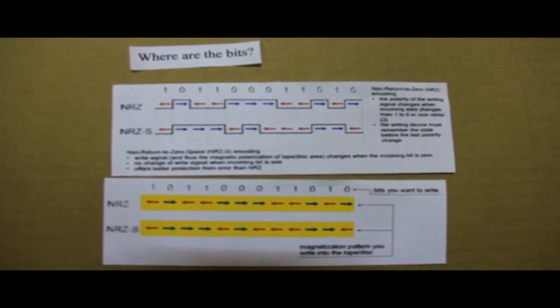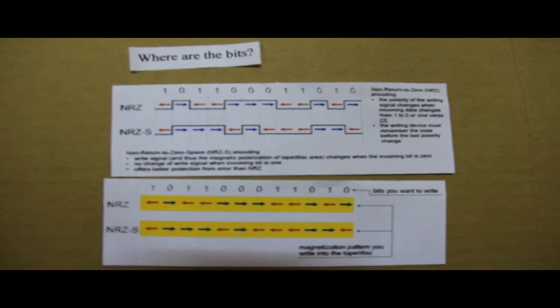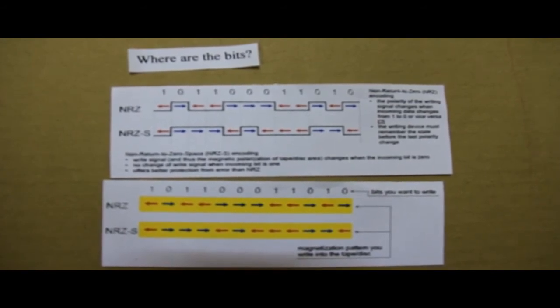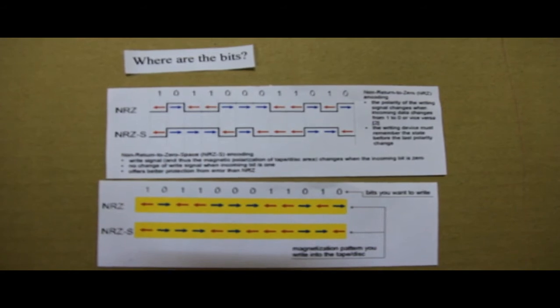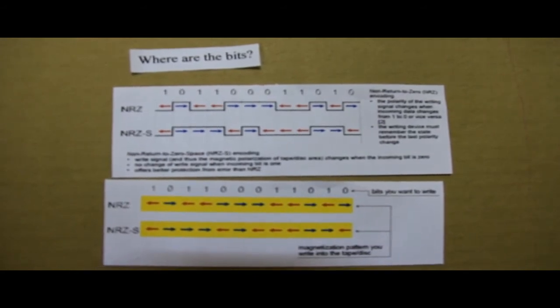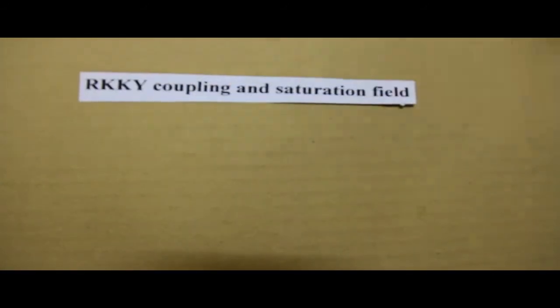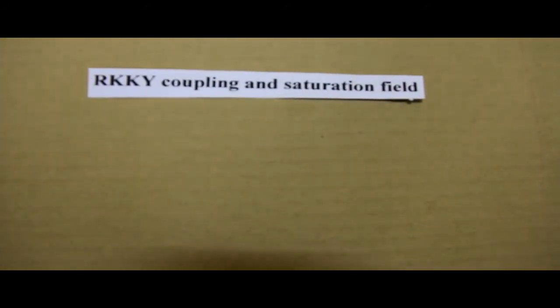This is equally true for readout with inductive heads, where the signal is proportional to the tape or disc speed, as well as for magnetoresistive heads, AMR, GMR, TMR, where the resistance is read out as a voltage from a field sensor. There are many ways of encoding data by series of flux reversals. Here, two examples are shown.